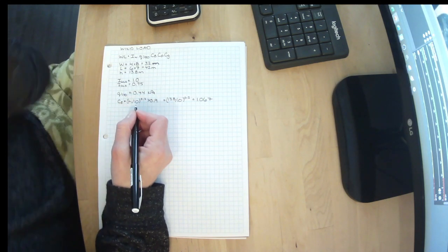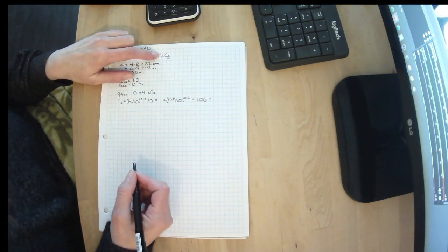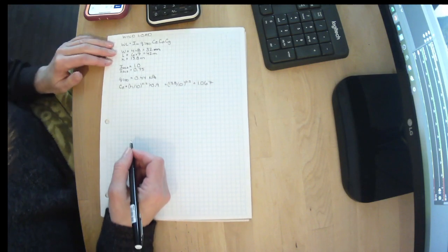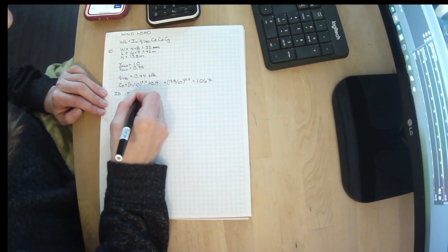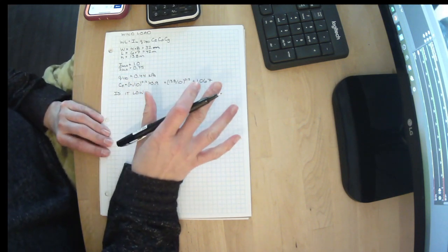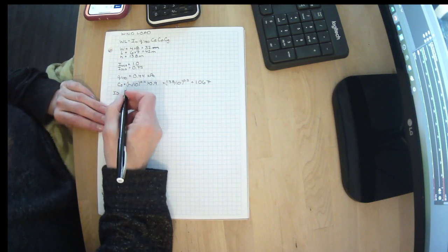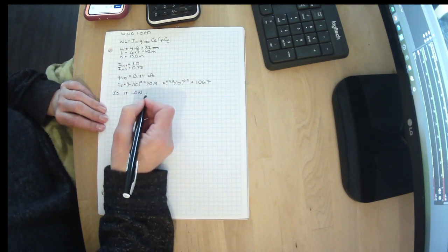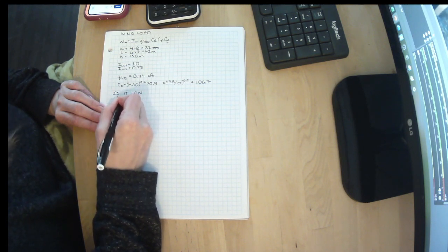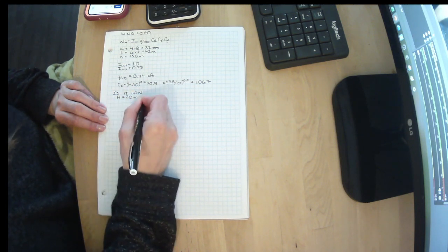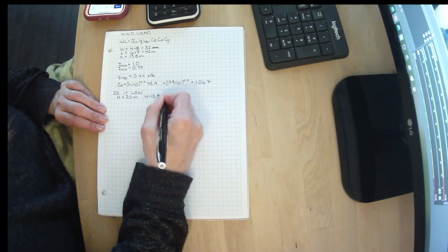We need to know if we're doing a high-rise or a low-rise building for CPCG. So is the building low? Again, you're not going to have to worry about this. I'm only going to give you low-rise questions. This never even used to be something that I needed to worry about, but H needs to be less than 20 meters. Well, H equals 13.8. We're good.